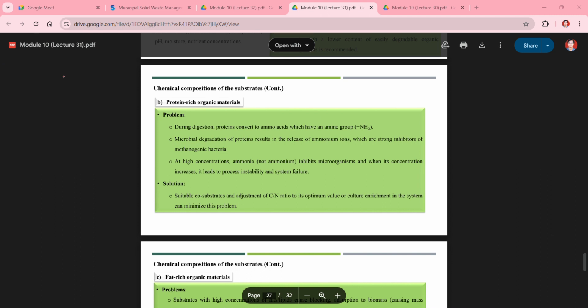Then what is the percentage composition of hydrogen in biogas from the anaerobic digestion process? So that has to be in the range of around 0 to 1 volume percent. Generally, the composition of biogas contains a major amount of CH4, around 60 to 70%, and CO2 gas around 20 to 30%, and there will be some other hydrocarbon gases also in the biogas composition.